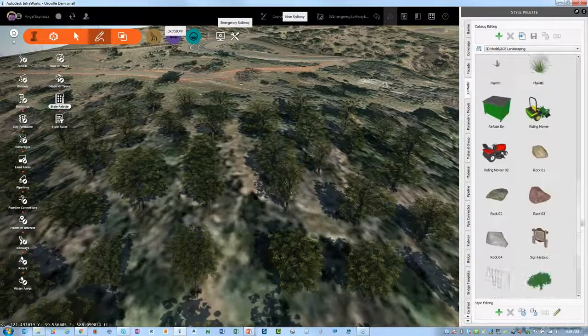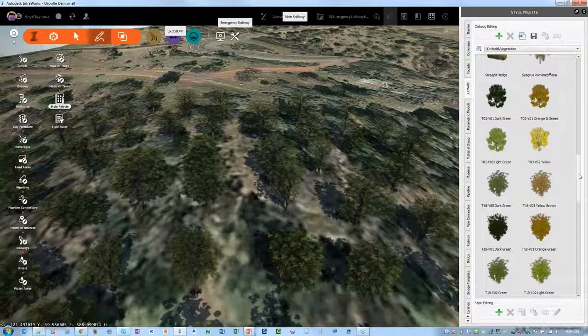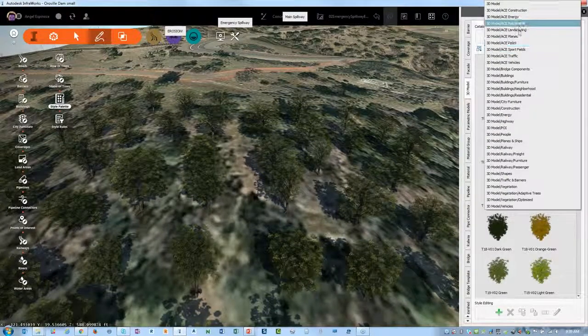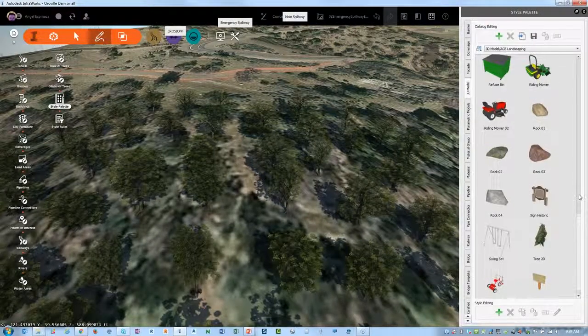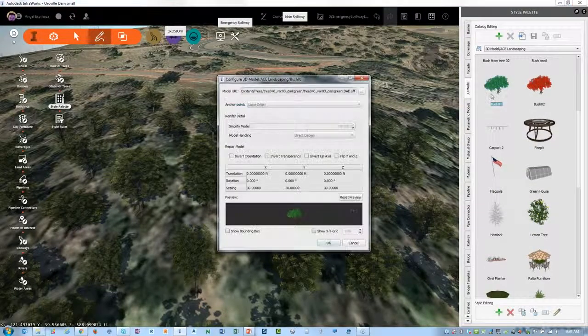So what I just dragged and dropped were these 2 right here. So what I'm going to do is I'm going to rename it, and I'll very simply call this bush 01. And the next one down, let's go back to my catalog, landscaping. And here's the other one, and I'll call that one bush 02. Okay, and go back to that. I'm not sure why it's jumping today. But now as I look up here for these different bush 01 and bush 02, what I'm going to do is take that